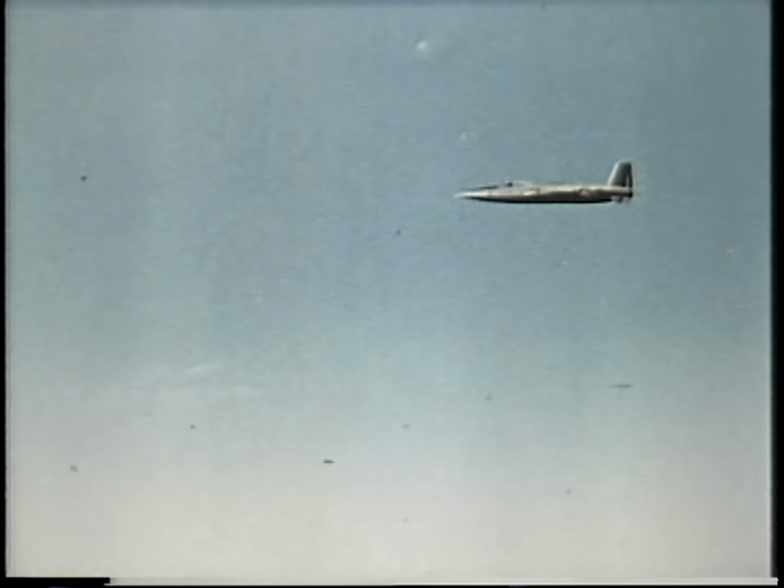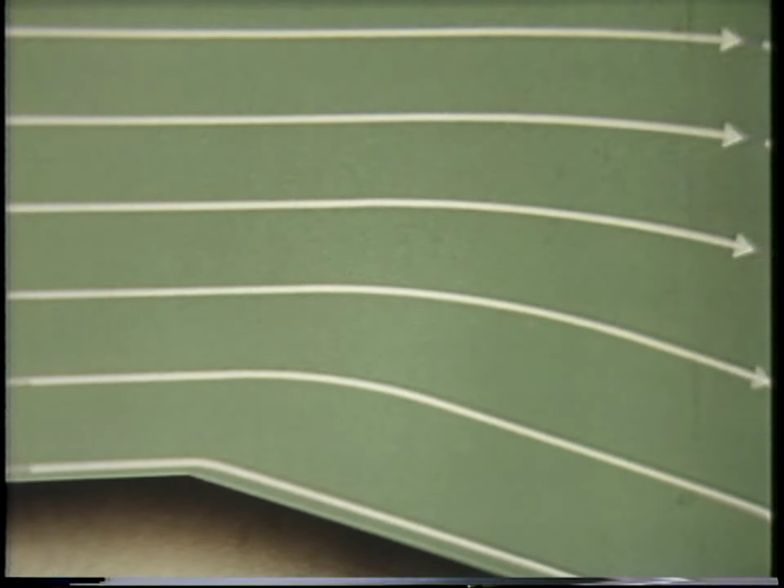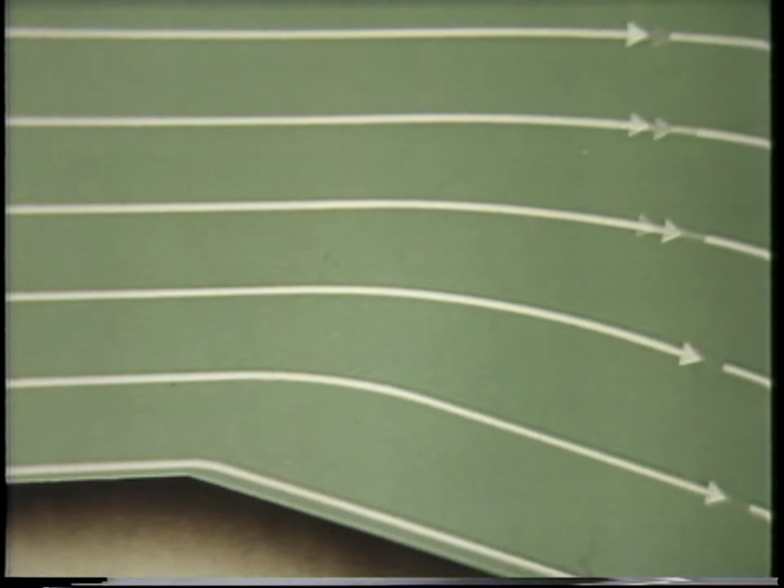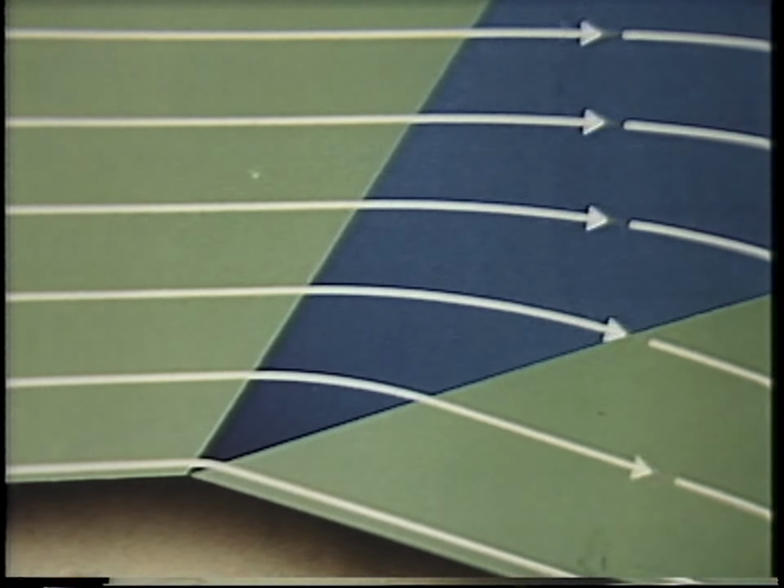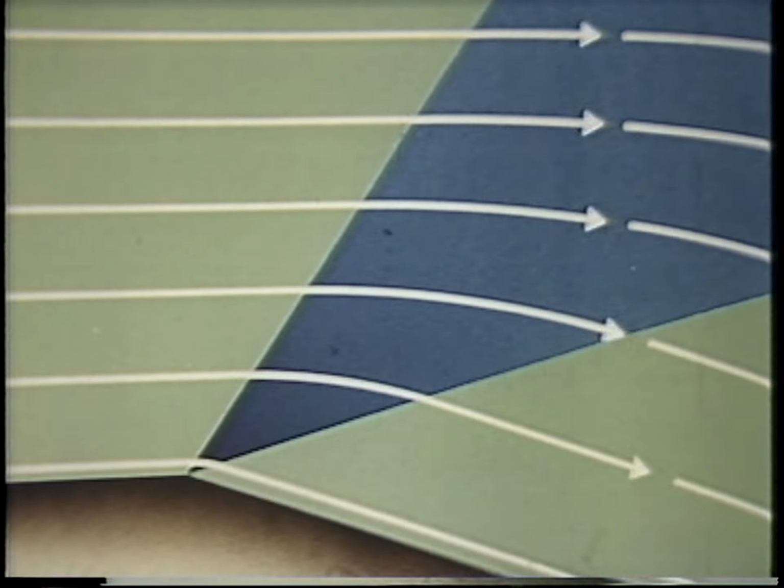In supersonic flight, the air flowing past every part of the aircraft is supersonic and behaves quite differently from subsonic airflow. Here's a section of a supersonic wing. The sudden corner on it couldn't be used on a subsonic wing, for, as the smoke shows here, subsonic airflow becomes turbulent and confused past the corner. But supersonic flow, surprisingly enough, can turn the same corner easily, as shown in this diagram. As it does so, the air expands through the region shown here in blue, and pressure is reduced.